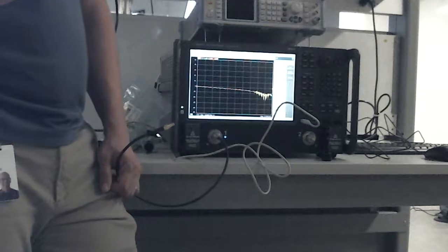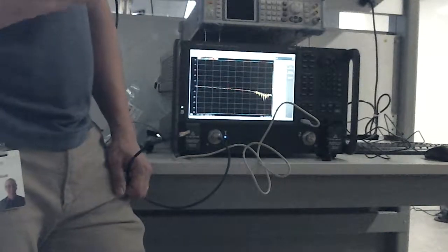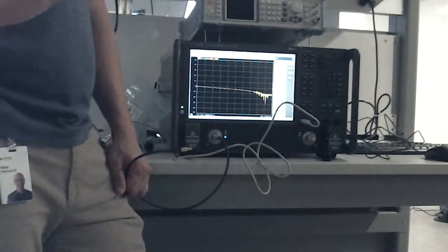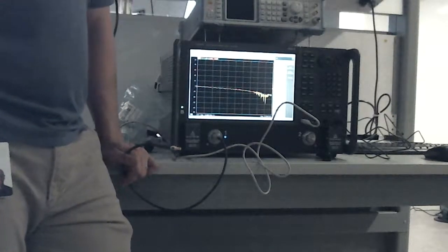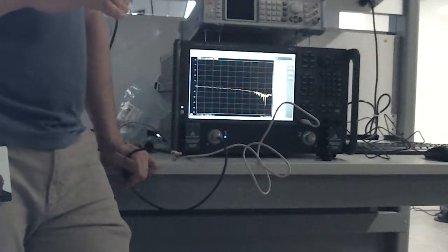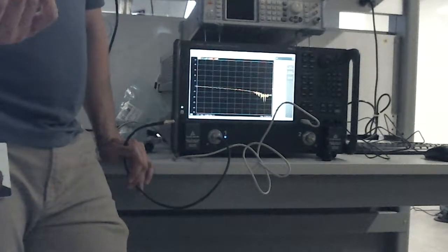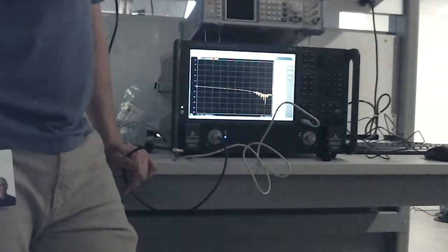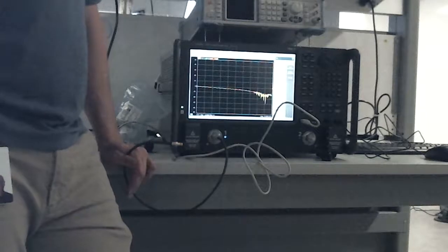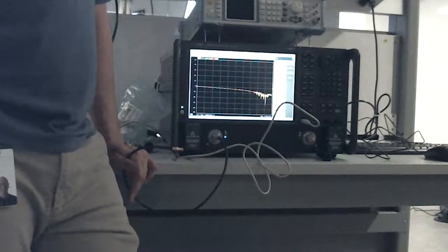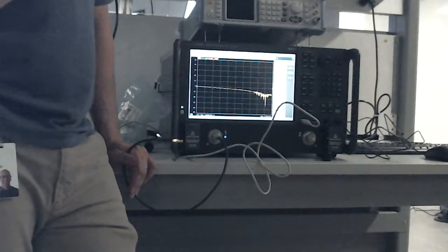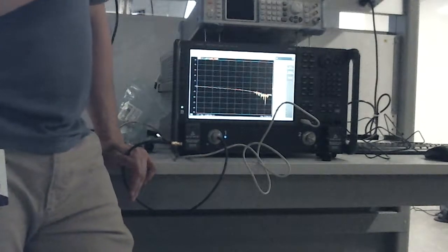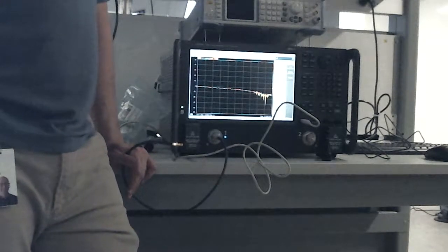When you're using a vector network analyzer, what I really recommend is that you think about the quality of the cables that you're using, because I'll show you guys some ideas of this. You're applying error correction that's not just a magnitude offset, you're applying corrections to all the error terms, so the reflectivity, directivity, phase tracking.